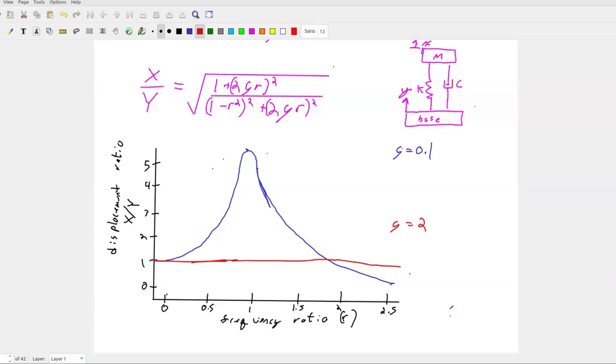So that's where you get vibration isolation or a sink or a well. It can be called a vibration sink or a vibration well. And you might want to operate a system at a frequency where you can put a lot of displacement in and you don't actually get a lot of displacement out. So let's fill in a few in between.